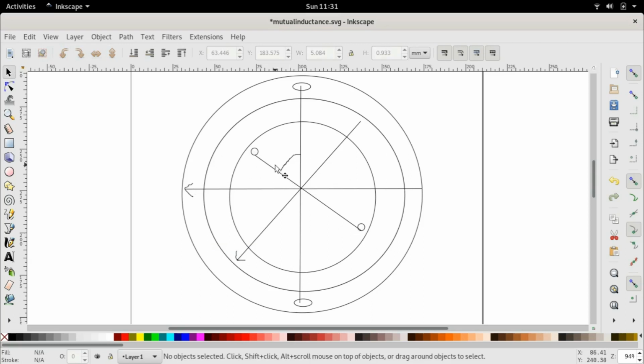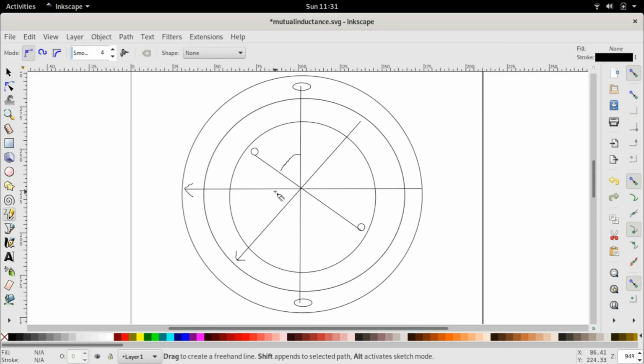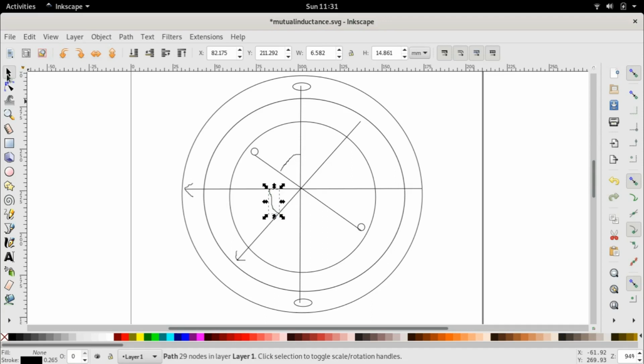Now, since we have a certain rotor position angle theta m between the stator axis and the rotor axis, there will be this exact same angle theta m between the stator flux and the rotor flux, right? So we can draw that here as well. This is the angle. So the question then arises, what will be the linkage of this rotor flux with the stator?